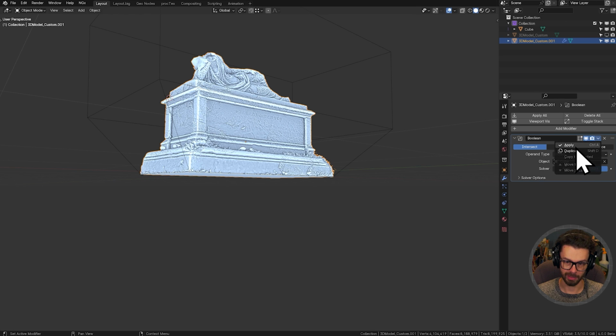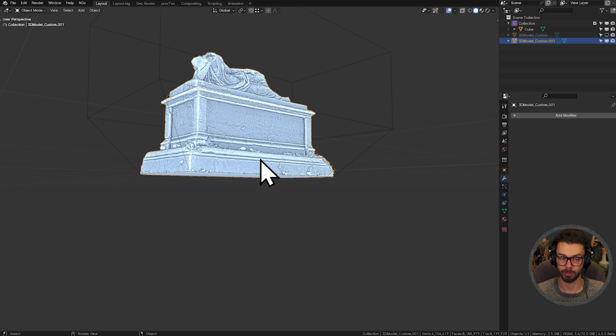Let's go ahead and apply this Boolean modifier. I don't want to have that kind of proceduralism active on a mesh that is this complicated. Let's apply this. And this is where we can make an optimization if you're confident about your Booleans. A modifier will be computed when you first create it, make it visible, and also when it is applied. Rather than doing all of your Boolean computation, both when you actually set your cutter and then when you apply it, if you have a cutter which you're confident about, you can simply disable your modifier, set the cutter object, and then go straight to applying it.